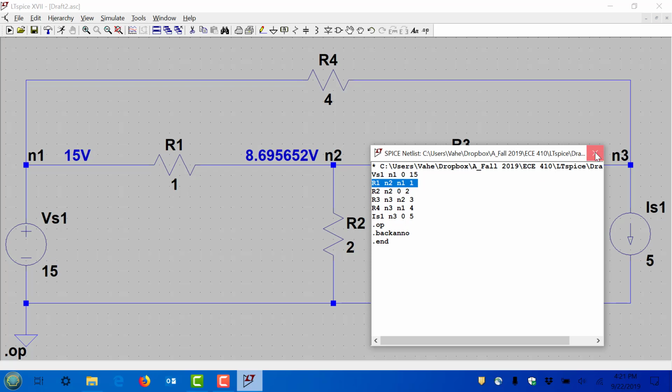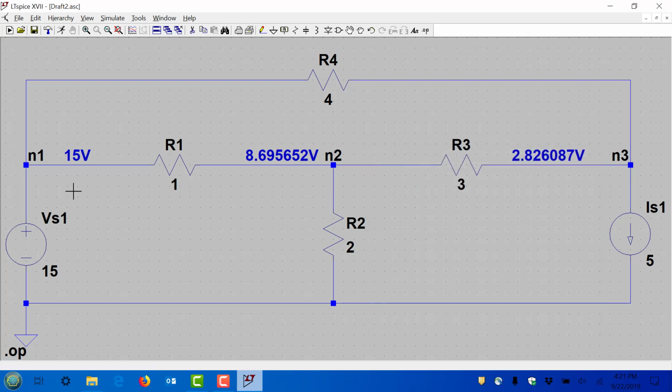So it's giving you the current from here to here. And that's why that current is negative. So we're both talking about the same thing, but we're measuring it differently. And that's why I kept on saying in class that it really depends on the way you measure it, because once you build a circuit and run it, there's only the voltages and currents that are present in the circuit. So if you measure it the opposite way of the way they are, right, you will get a negative. But it doesn't change what the circuit actually does.